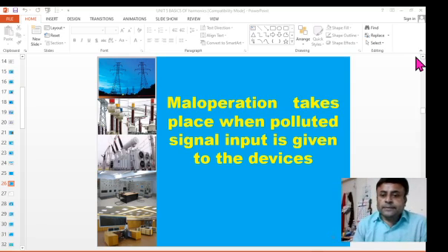This is the difference between other power quality parameters like sag, unbalance or interruption, and the harmonic wave, because other waves may be non-sinusoidal aperiodic, but the harmonic wave is non-sinusoidal periodic. Therefore, it is possible to apply Fourier series.